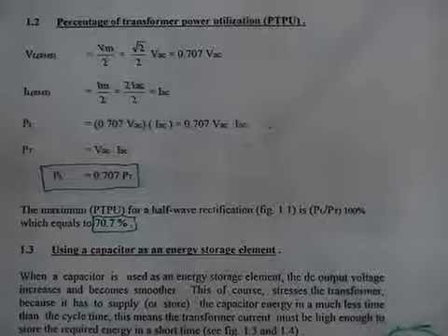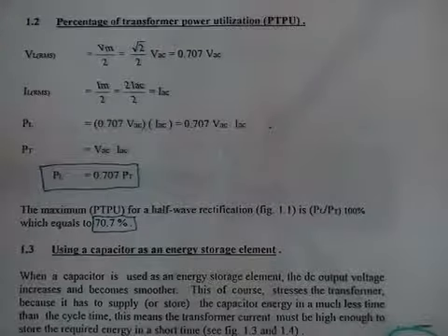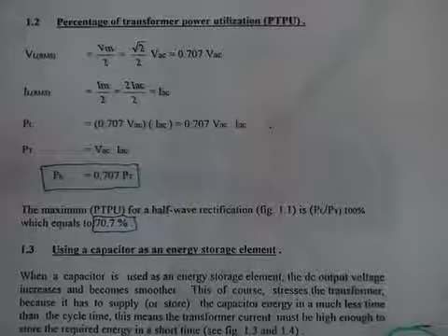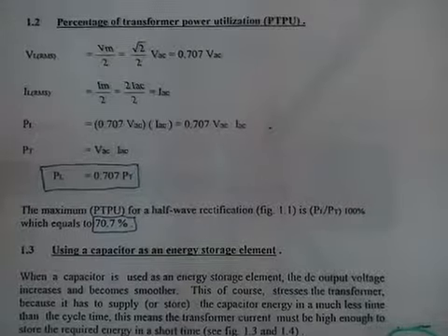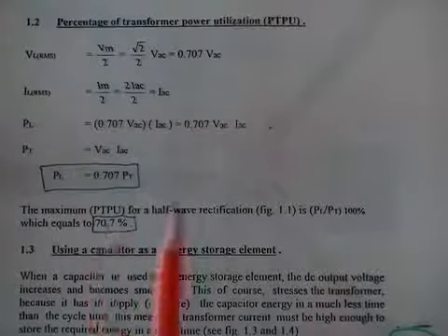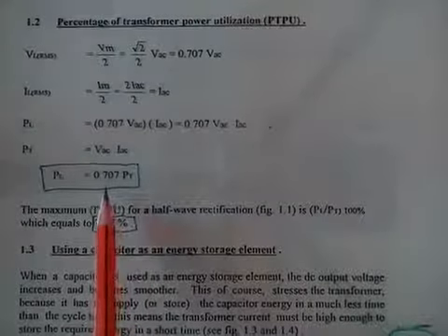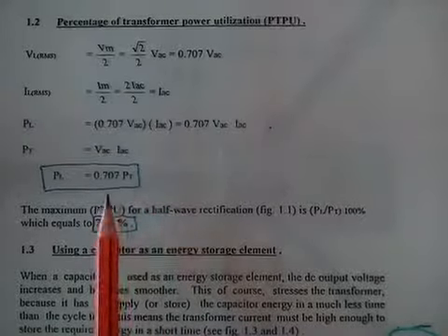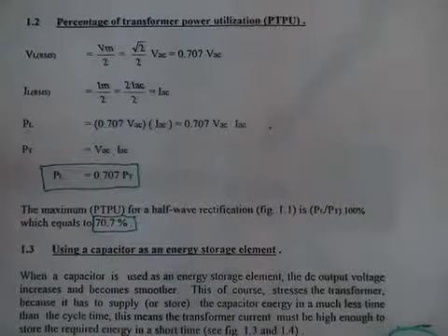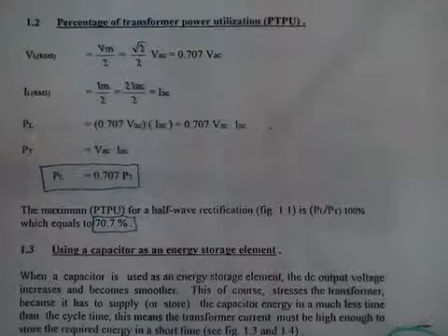We are able to get up to 70% of the power of the transformer in the load. So that means we paid for 30% that we are not able to use. You can get up to 70% without exceeding the specifications of the transformer.